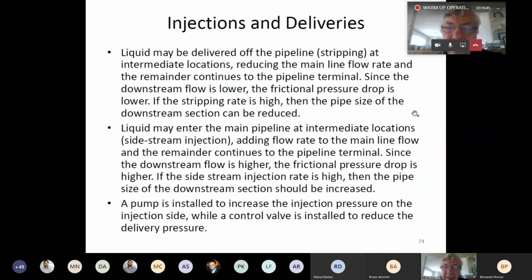How do we control that? Well, you control the fluid flow from a control center. It's continuously measuring pressure and temperature at compressor stations, pump stations. It'd be looking at vibration levels. It would be checking on the volumes, the height, capacity of tanks, so that you know whether the tank's full and whether you can put more fluid in there or not. It also looks at the status of the valves along the length of the system to make sure that they're open or closed. That's how you exercise control.